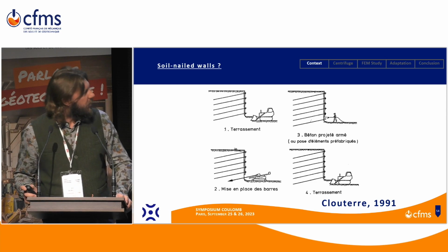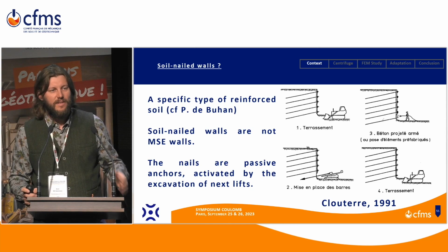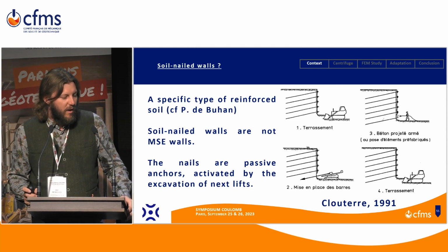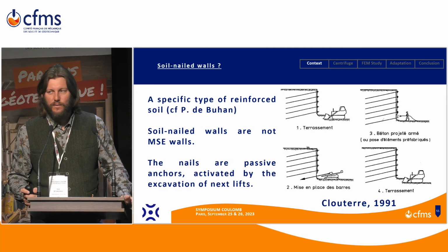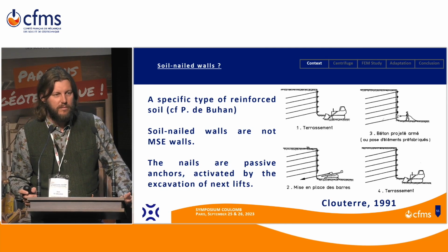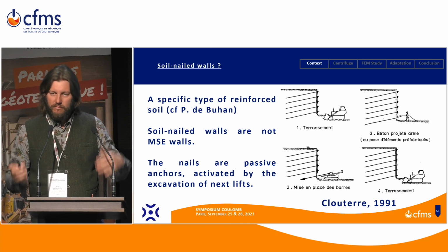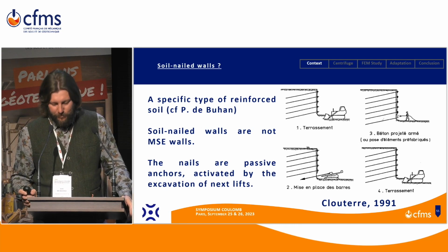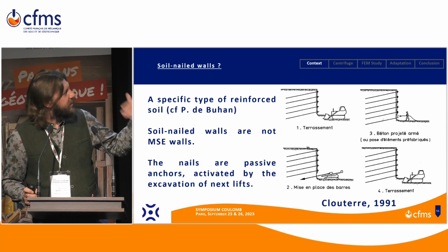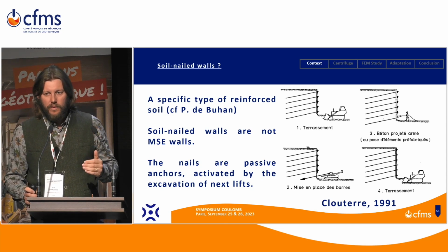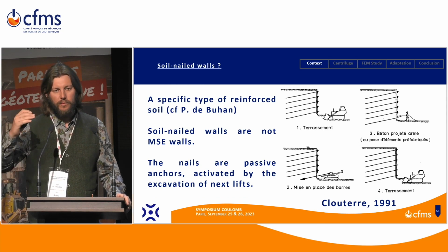So what I said is, it's a type of reinforced soil, but it's not exactly the same thing as mechanically stabilized earth, even if they are very often presented together, because in the end, you have a soil with a reinforcement rather regularly spaced, but the phasing is really different. As I said, for soil nailing, it's an excavation process, and for the MSE walls, it's a backfill process.